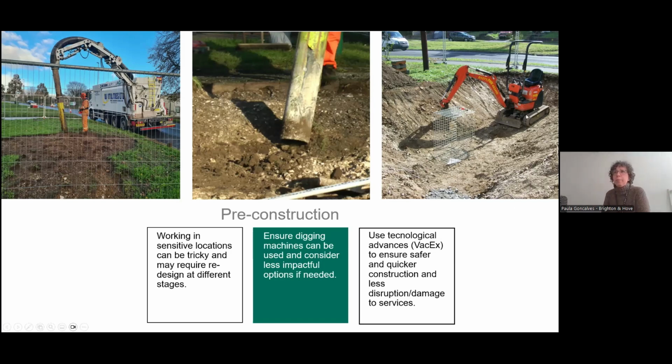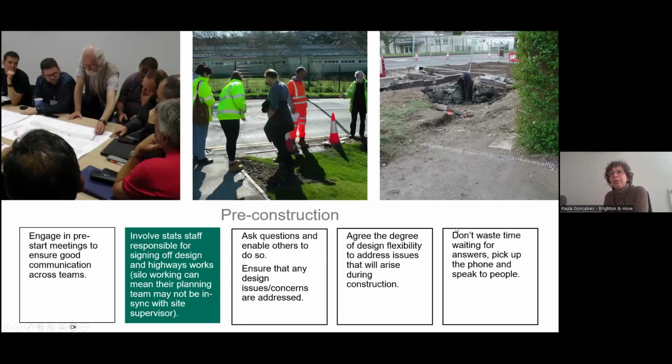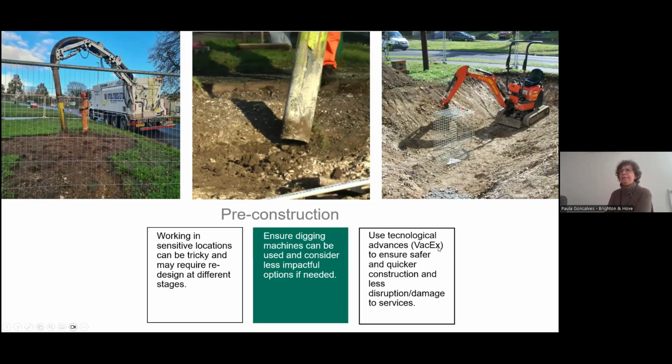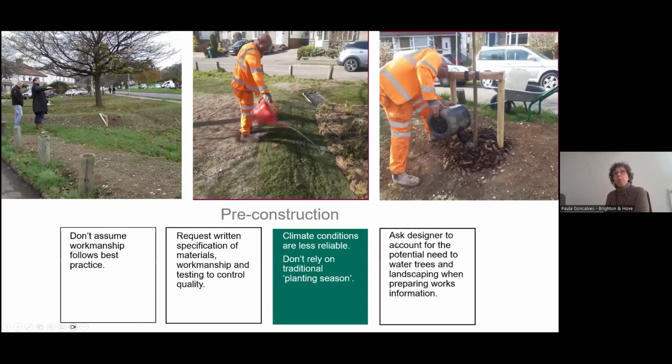The other thing is, in some places, when the constructors were doing this, the builders, the contractors had never done SuDS before, but it was a good learning curve for them and for us. And you shouldn't really have machines on top of SuDS because that compacts the soil, and then you can't plant anything on top. So there are little bits everywhere for everyone to learn. Sorry, I was going to say the name of this machine is VACX, if you want to know more about it.